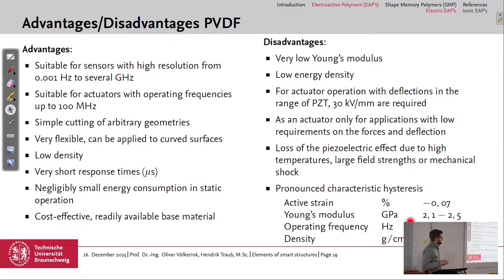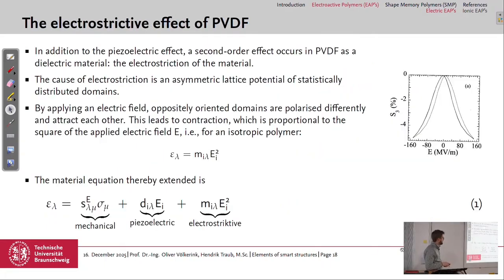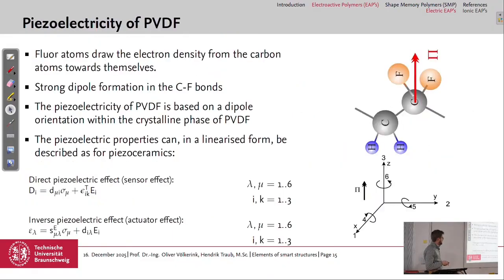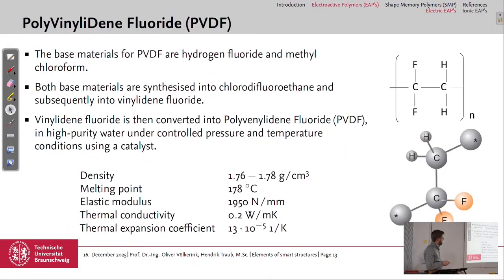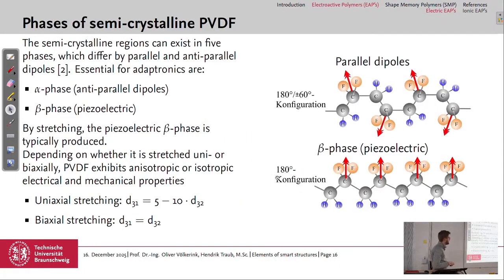The Young's modulus written down here is about 2, similar to what I had on the slide before, maybe slightly higher, depending on the manufacturer and the data sheet. And a density of 1.47, also a bit different than what I had on the slide, but it always depends on the data sheet and the manufacturer. You take the numbers out.